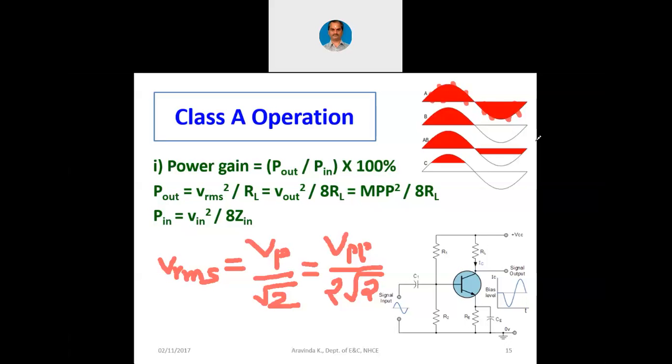One peak is around 350 volts because it is a continuously changing wave. You can see here, it is a continuously changing wave. Whereas we equate it to DC because we know that it will have the same effect as the DC when we apply it to a resistive load. That is the purpose of finding out the RMS value.